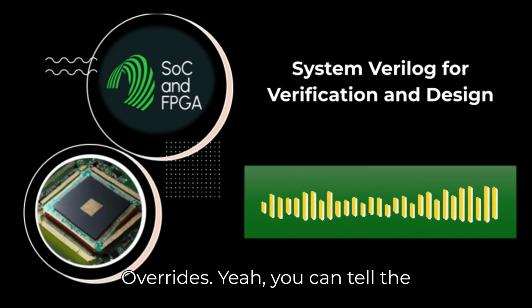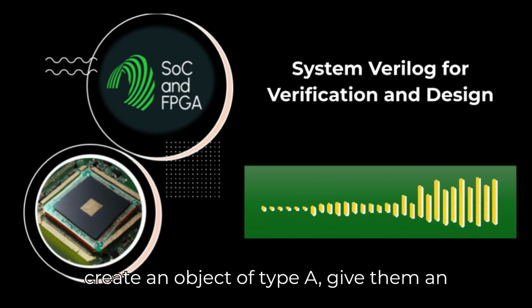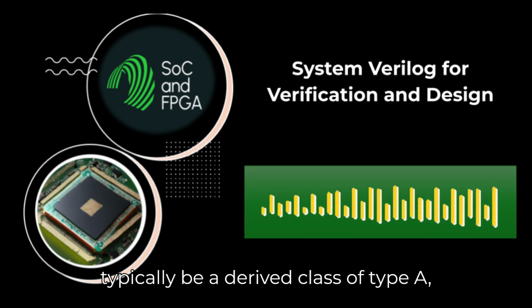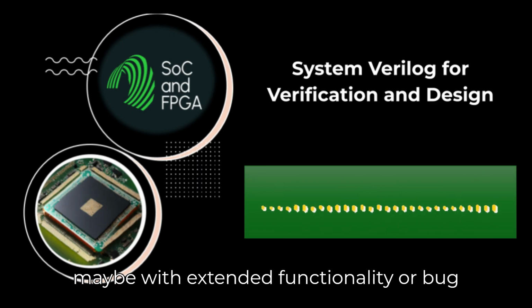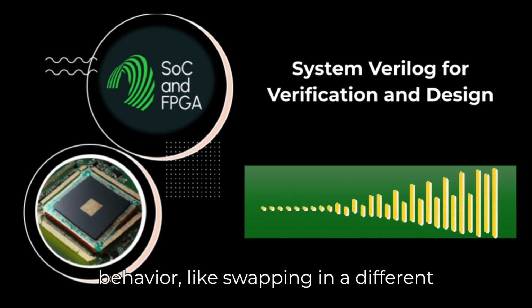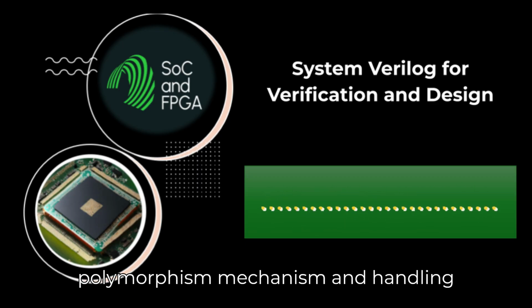Overrides. Yeah. You can tell the factory, hey, whenever someone asks to create an object of type A, give them an object of type B instead. Type B would typically be a derived class of type A, maybe with extended functionality or bug fixes. This lets you modify test bench behavior, like swapping in a different driver, without changing the test bench structure itself. It's a powerful polymorphism mechanism.